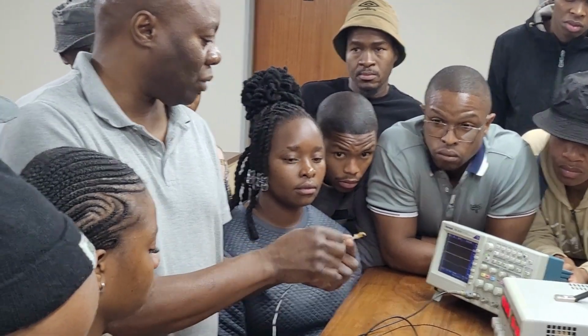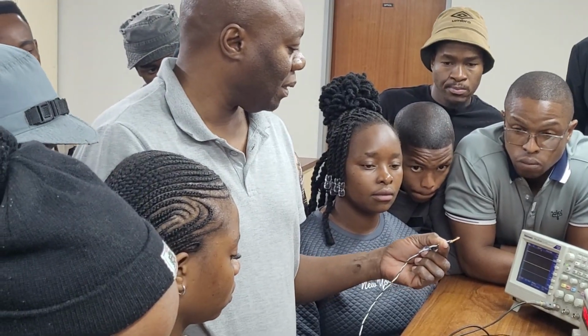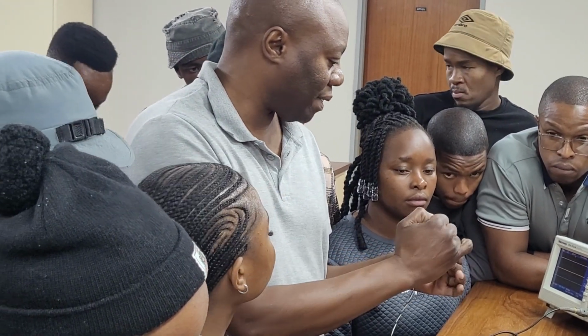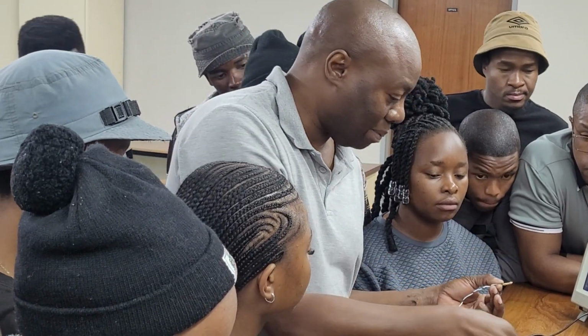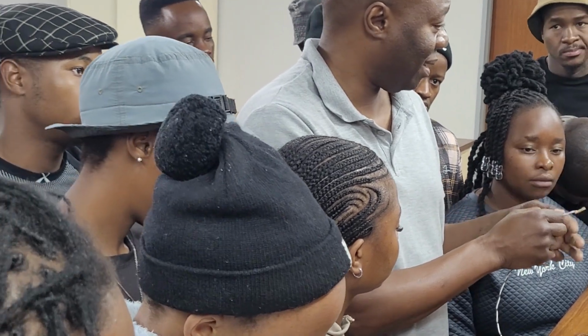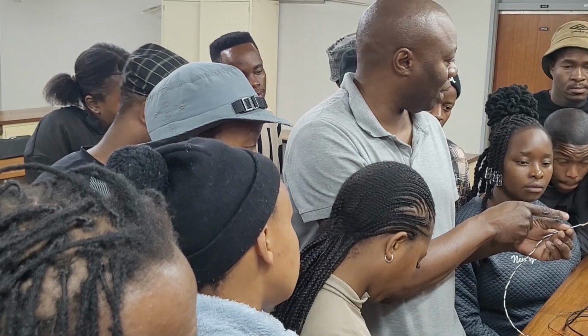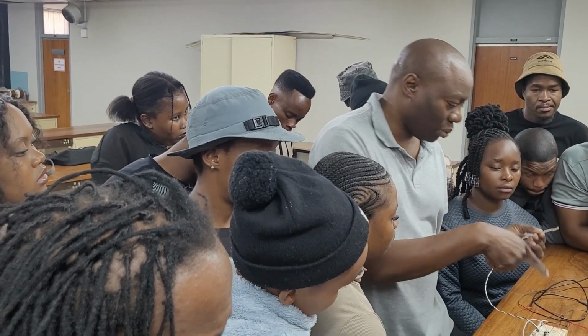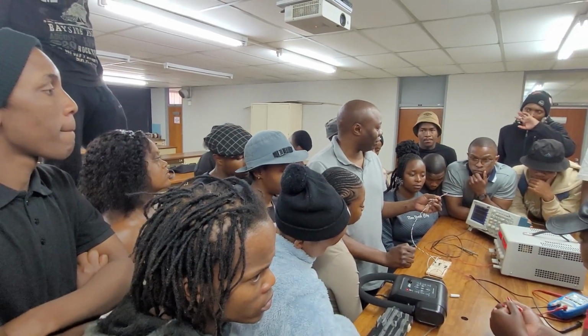And I soldered it onto Veroboard like this, just to give it a form. Okay? And I've stuck it down with double-sided tape and biased it because it needs to be biased. There's a field effect transistor in here, okay? That you need to supply with power before it will do what it's supposed to do. So this 10K resistor is just to bias that condenser microphone, okay?